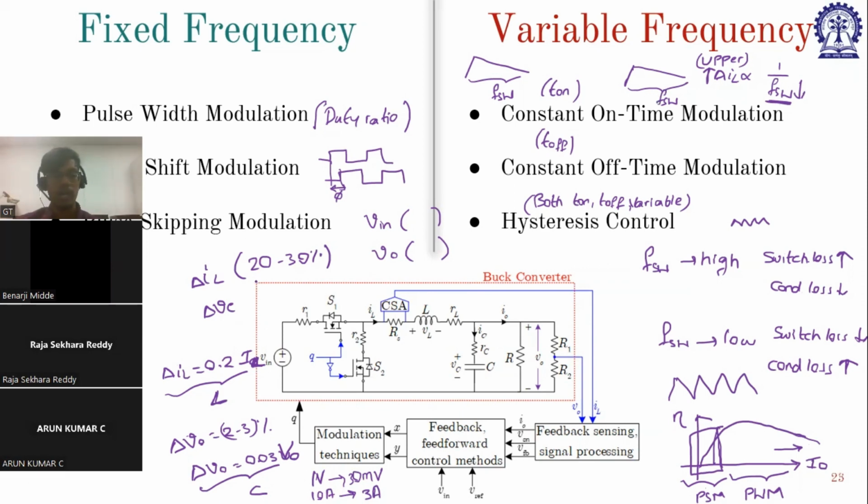Whatever you are considering for the designing of L and C, what is happening is I'm getting peak to peak ripple as 200% and not 20%. But still, the output voltage is maintained constant. Even if we connect, say, a load, the load current is actually a flat line, but the inductor switching current is actually reaching 200% or 300% of it.